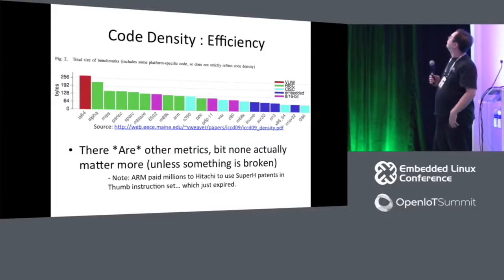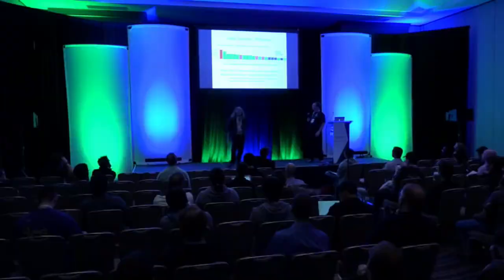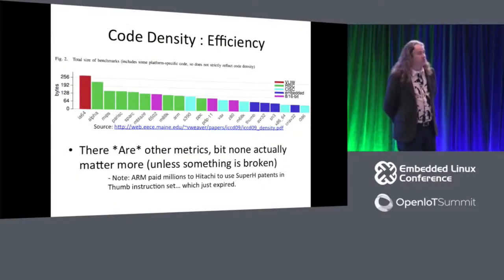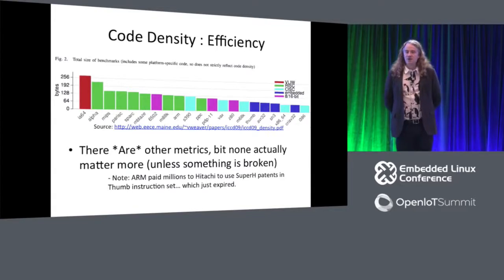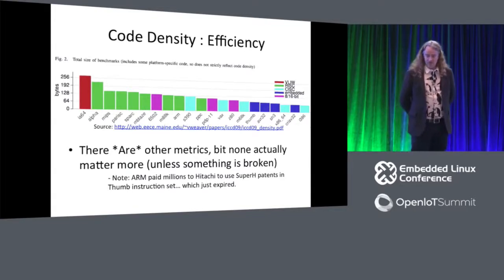So the SH architecture had a couple of different things about it that were very important. The first of which is instructions are fixed length. And that's important if you're trying to make very, very small hardware. You don't want instruction decoders that are difficult, that have a big finite state machine in them to deal with taking unaligned instructions and reassembling them and all of that stuff. These were the original ideas behind doing RISC in the first place. Exactly. And so SH took an approach that everybody else was scared to do, MIPS and ARM and all those guys.